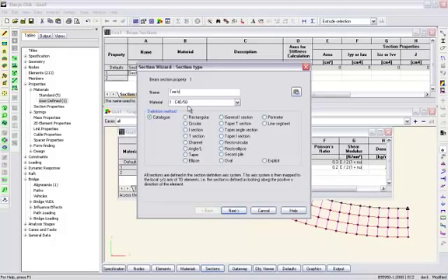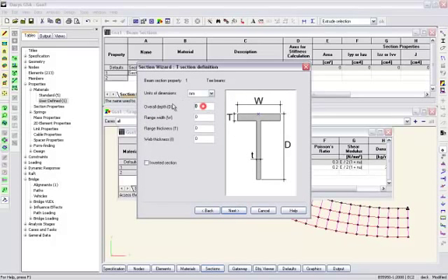Longitudinal T-beams. Overall depth a meter. Now we're at 3 meter spacings. Flange 500 thick, and the web. This is the deck. Nope, got the wrong way around. That's better. Flange, deck, web 500s.